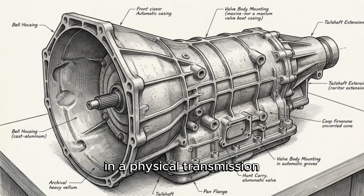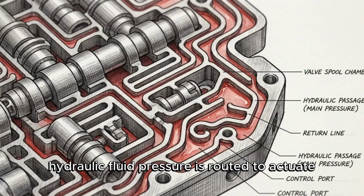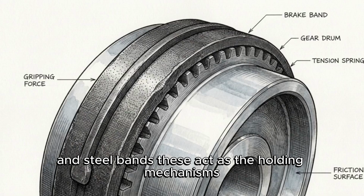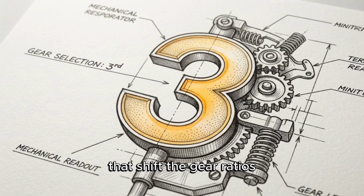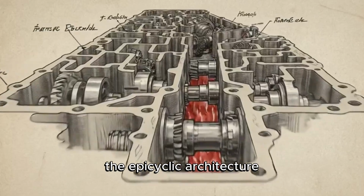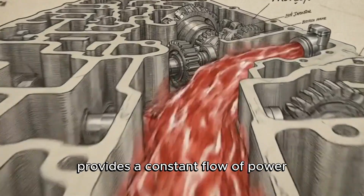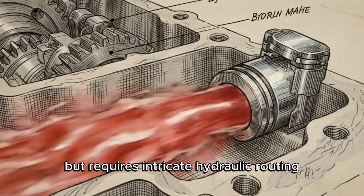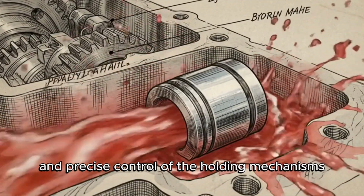In a physical transmission, hydraulic fluid pressure is routed to actuate multi-plate clutches and steel bands. These act as the holding mechanisms that shift the gear ratios. The epicyclic architecture provides a constant flow of power without shifting gear locations, but requires intricate hydraulic routing and precise control of the holding mechanisms.